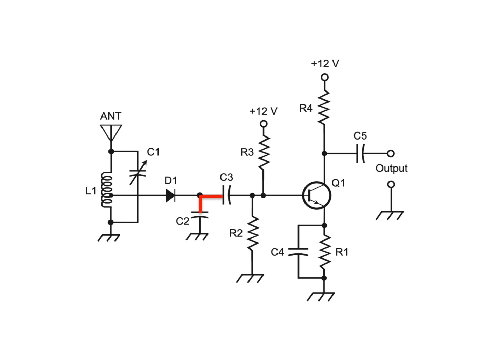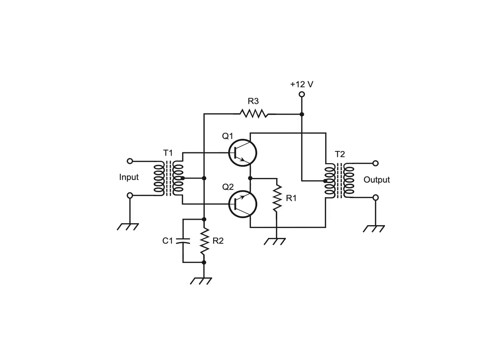This circuit has a low audio output power level, although it's a lot louder than the feeble audio signal that comes from the crystal radio all by itself, which gets its power only from the signal current in the antenna. Nevertheless, even the amplified audio at the output of the circuit here isn't enough to provide a comfortable listening volume in a loudspeaker. In order to boost the audio power level some more, you'll need an audio power amplifier. This shows a two-transistor circuit that will perform this task. It's called a push-pull circuit.